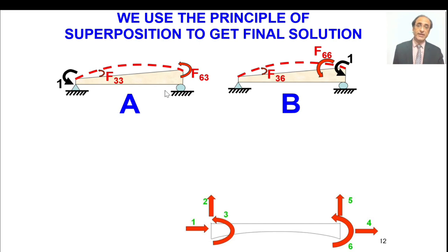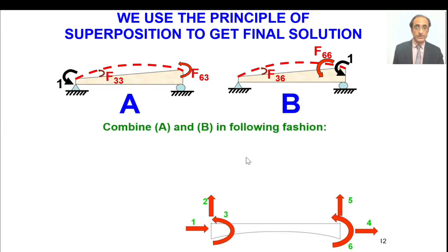So the point is, can we superimpose these two systems A and B and achieve a condition such that we have displacement only along one particular degree of freedom, that is the rotation, and all other displacements are locked? Yes, this is possible. If we apply the linear combination of A and B such that we are able to lock all rotation at the right end of the structure by their linear superposition, then we'll achieve this kind of system.